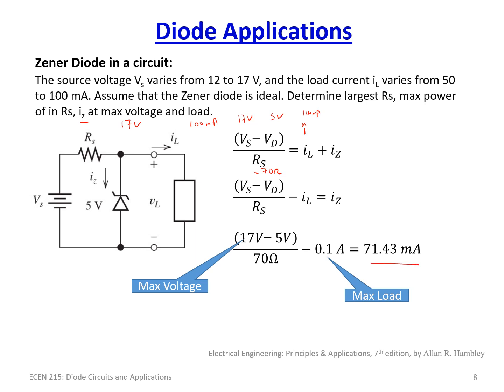71.3 milliamps. Now, another thing you need to pay attention to is that we are dissipating power here. So the power in the Zener is equal to 71.3 milliamps times 5 volts, which works out to approximately 350 milliwatts. So that should be of interest here. This is important when you look at the data sheet for a Zener diode, if you're using it.